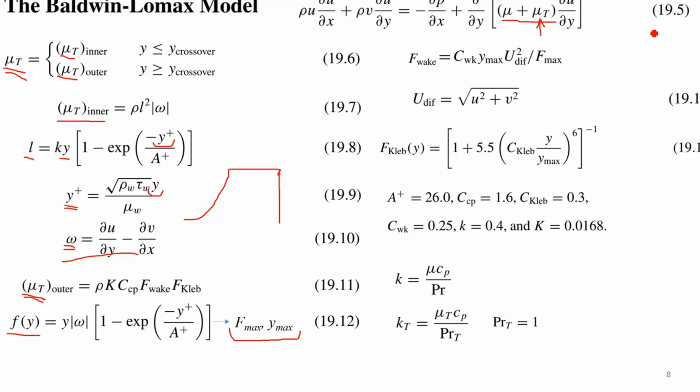They are included in the model and calculated inside the model, but they cannot be defined from outside, like temperature, pressure, or density. So pay attention that viscosity and heat conductivity for turbulence are not included in the list of thermodynamic parameters.